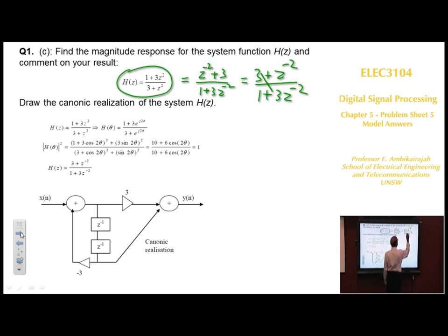Now we learned yesterday these coefficients are roughly the same, so in that case it will look like an all pass filter, but we'll prove that. So we wrote the thing here and we substitute; H(theta) is already substituted this way without transferring into this. You've directly substituted, which is possible. This is one way of doing it. And then you find |H(theta)| squared, which worked out to be 1.